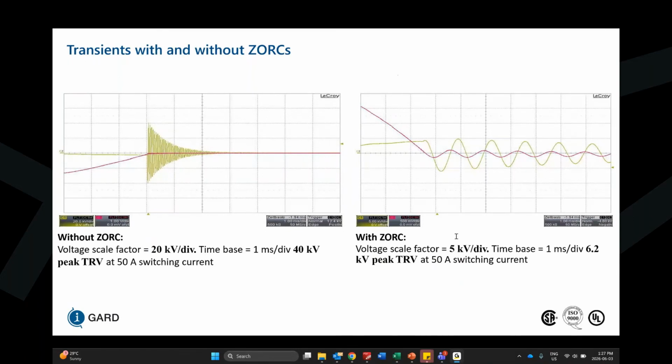Do you need to be coordinated with relays? No, you don't, because we're talking about very low milliseconds. So I don't think that this involves relay coordination. It's more so about just having it interconnected in your system to handle those high frequency transients when they come in. Hand versus spring or motorized?